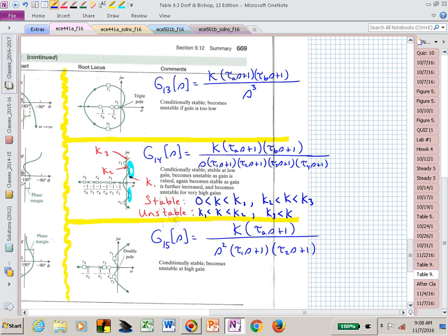What are we doing when we march up this imaginary axis? If we were evaluating our transfer function along that imaginary axis, I don't know if you remember me walking in 320, but I would pretend to walk up the j omega axis. That's the Bode plot. You're evaluating g of s, h of s, with s equal to j omega. Meaning you could use MATLAB to sketch the Bode plot with just a command BODE and the system in parentheses, and now you try to find at what frequencies that transfer function equals minus 180 degrees.